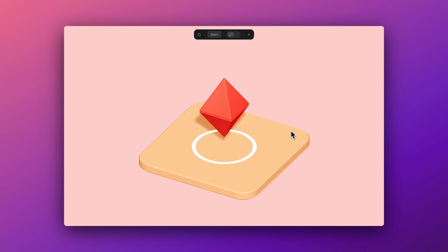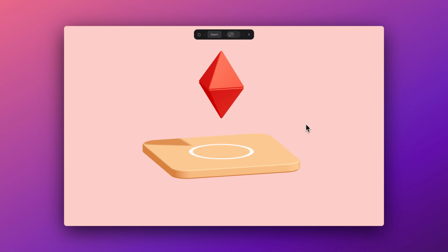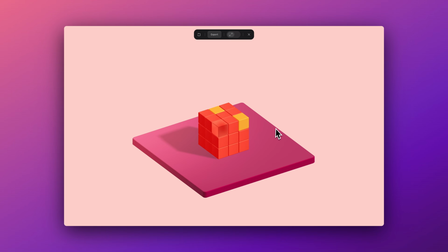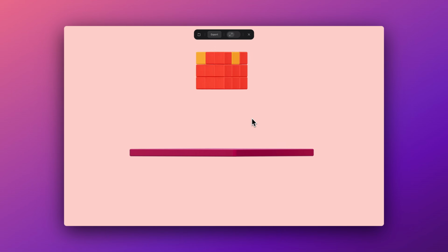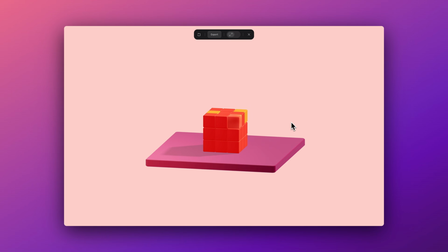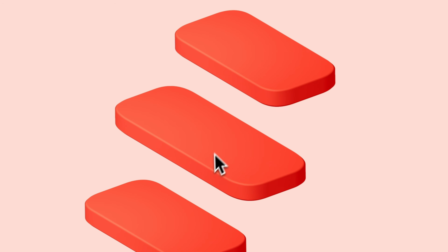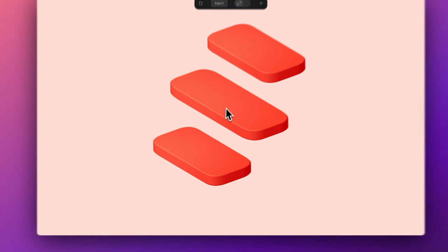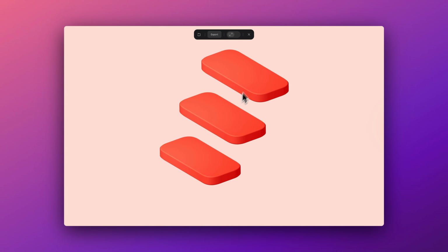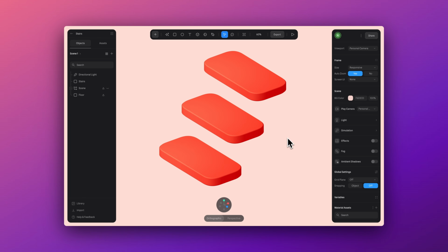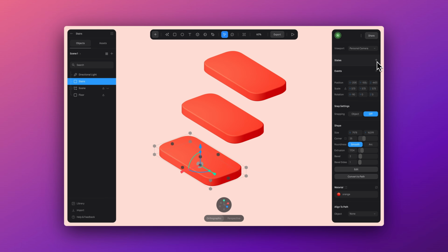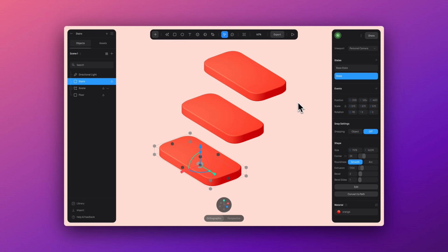So far we've only added some pretty simple animations, and they're looping, so we don't need to interact with them to trigger the animations. But what if we want some interactive elements in this design? So for example, we have this set of stairs. What if we hover over them, the shape of the stairs will change? So to do this, it's very simple. Select the stair and create a new state and adjust the Y size.